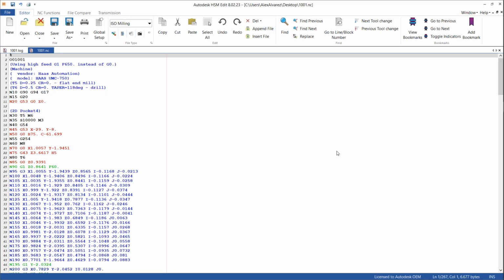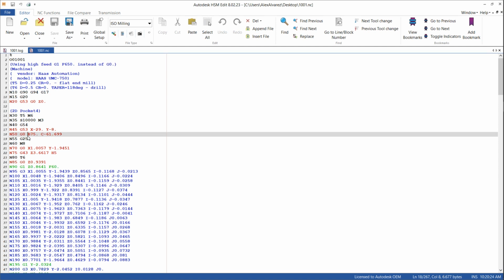And then here is your program, right? So the extra 2 axes in this case are going to be your B and your C axis, right? Essentially those are going to be your rotation around either the Y and the Z axis. Typically the A axis is what rotates around the X axis, right?